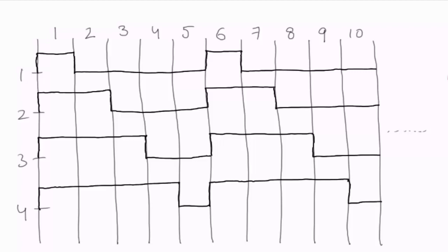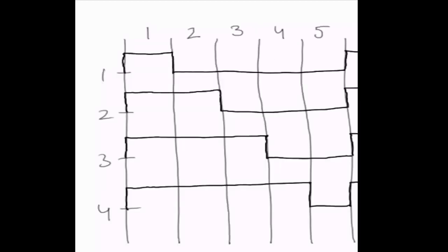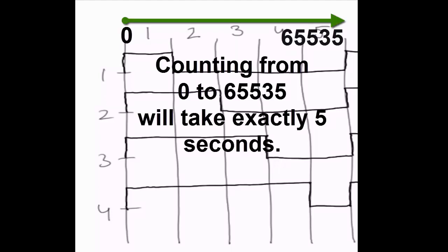Now we will understand how we will achieve this LED blinking behavior using timer 3. If you noticed one thing here, after every 5 seconds the behavior is repeating on all the LEDs. What we can do is assume this complete 5 seconds as a single time period. What I mean is I will set the timer to count from 0 to 65535, and this counting will be completed in this one single duration of 5 seconds.